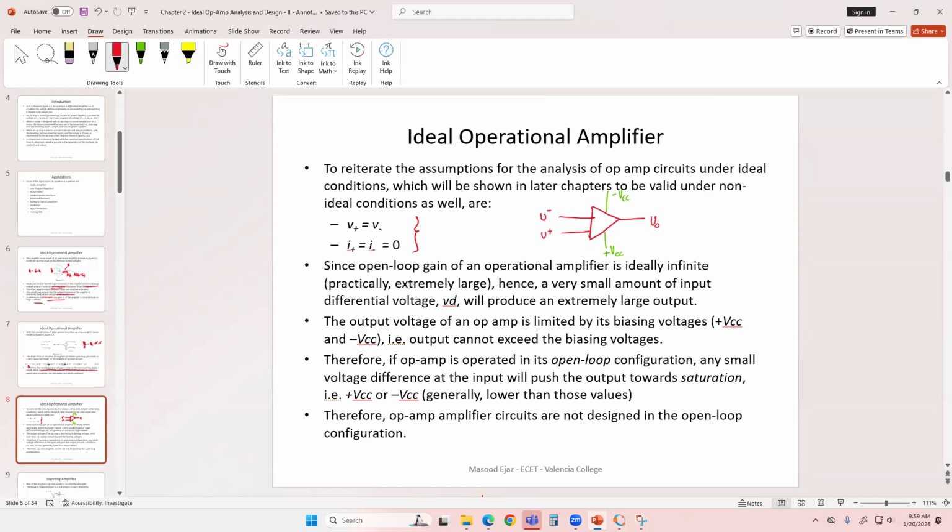Let's assume your gain is very large. Like for example, in today's quiz, your output voltage was what, 41 point something, right? 41.8 or something like that. Let's say that amplifier you biased with 15 volt and negative 15 volt. So the maximum swing you can have is about 30 volt, 15 and negative 15. And the output voltage is coming out to be 41.89 volt or so. Let's say that output voltage is centered right at 0.